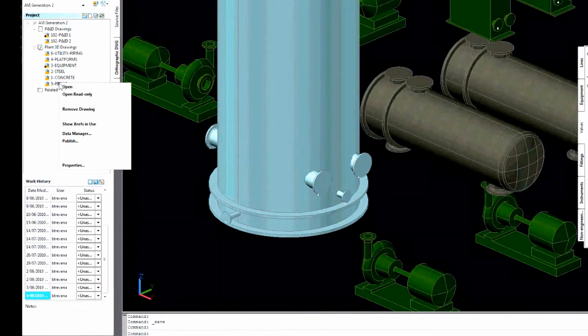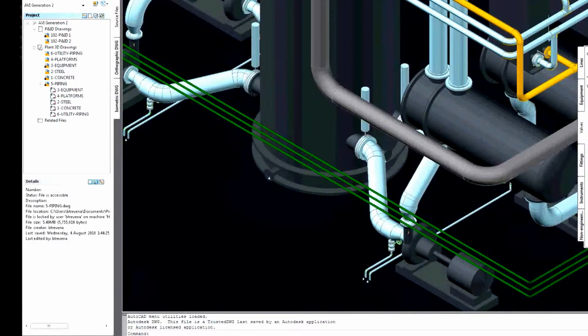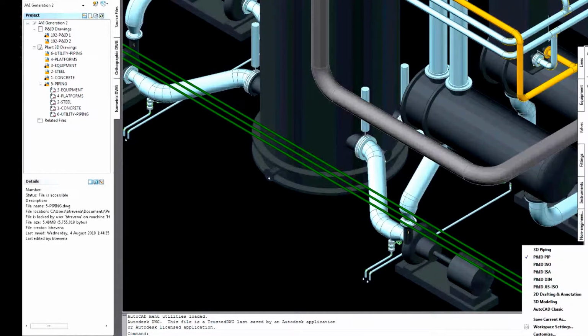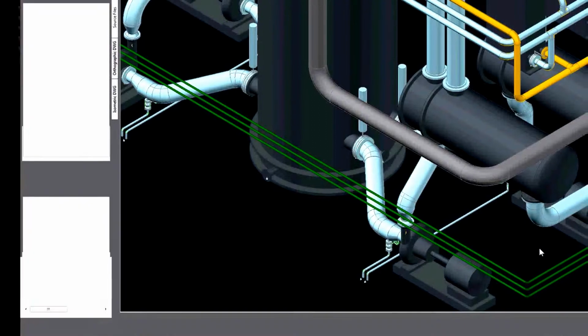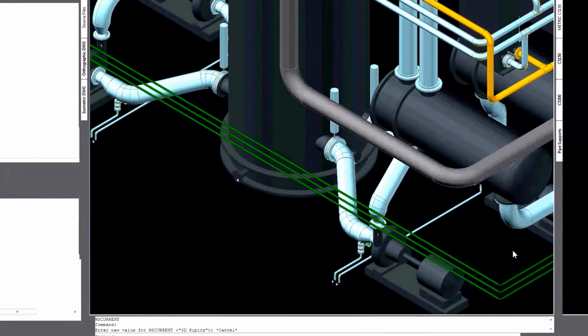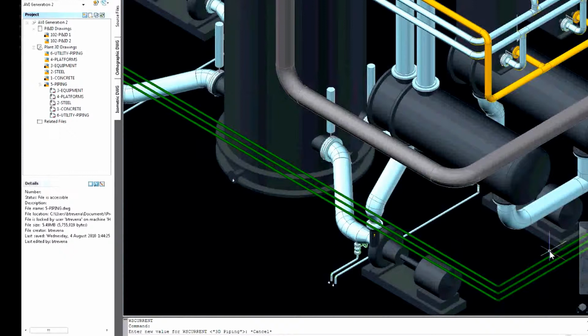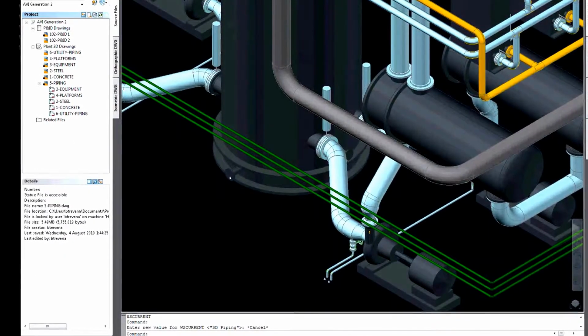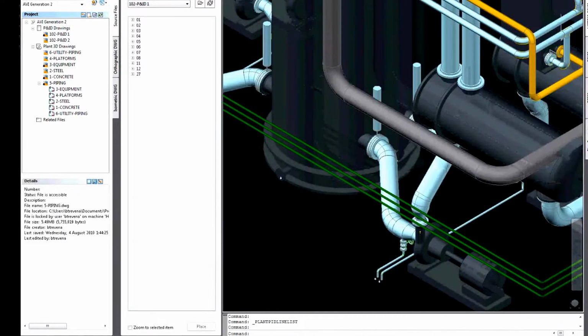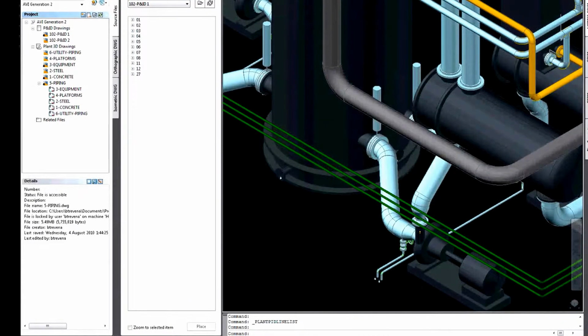Now we'll open our piping model. We have a palette that represents all the componentry within the nominated piping spec on the right hand side of the screen. We're not going to use that. We're going to run our line using P&ID line list view and drag and drop the physical parameters for our line by selecting the items from the P&ID.